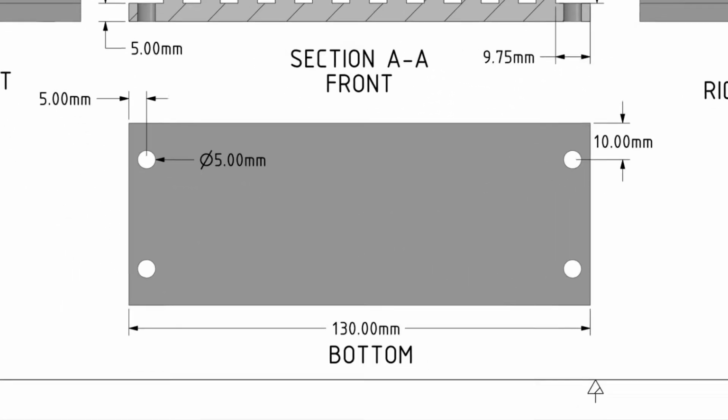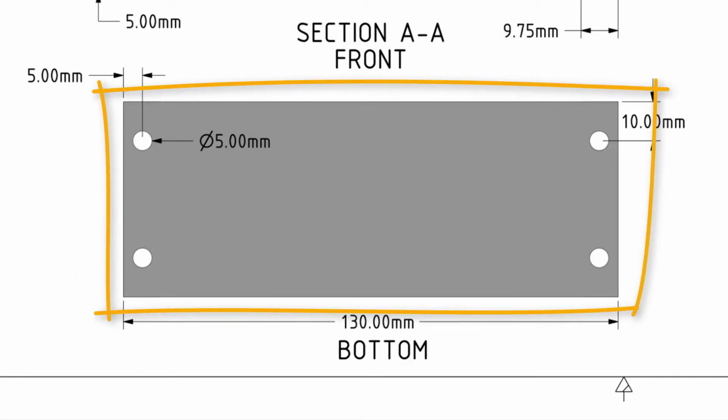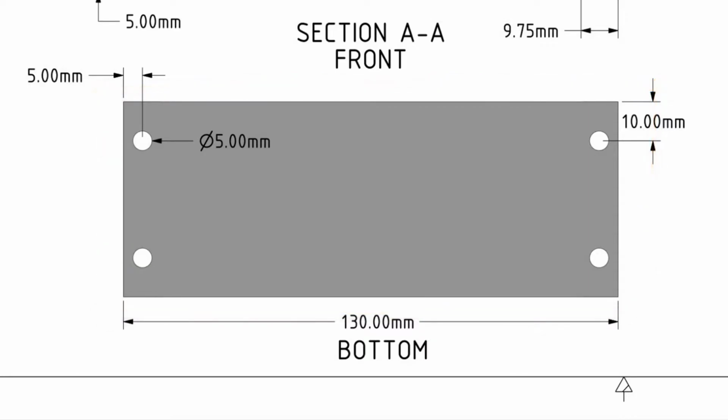Look at the drawing. The base of the heatsink is rectangular. We can sketch it and use the pull tool to easily create it. Once we have the base, we can build all the other features easily. The second step can be the creation of the 4 holes for the mounting screws. They are equally spaced from the sides and have the same diameter. We can create one using the pull option and then copy and move it to create the other ones. This would reduce the number of operations we need to perform.